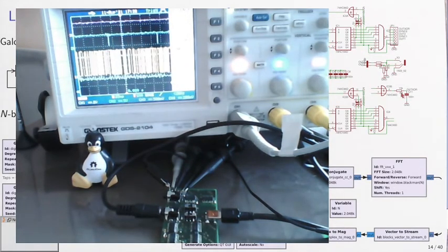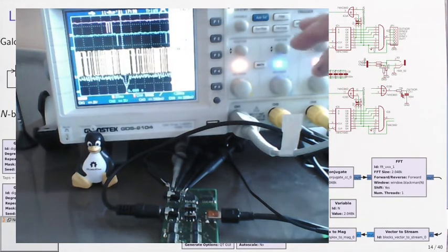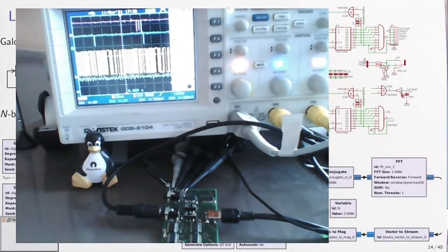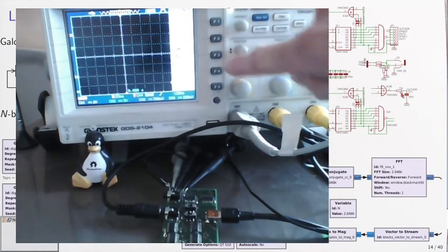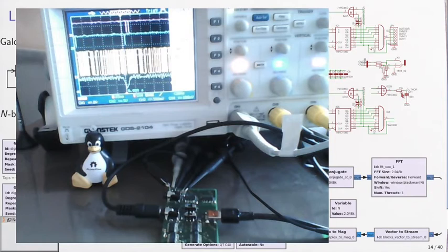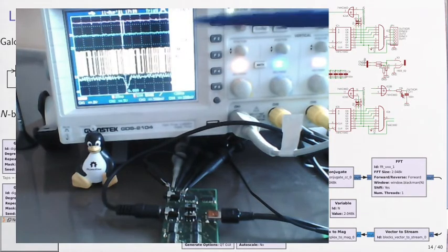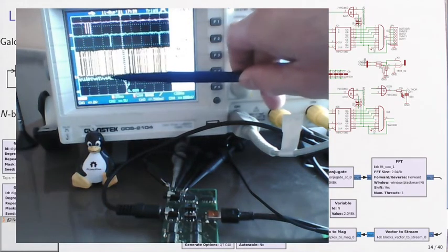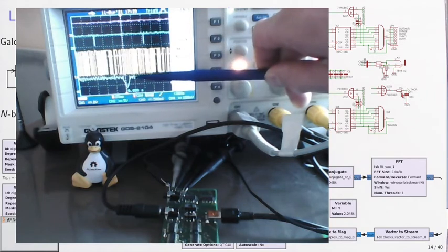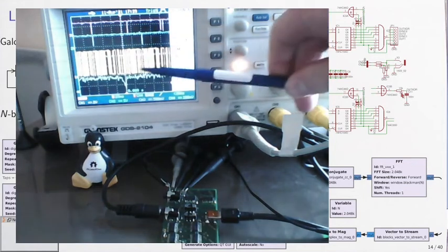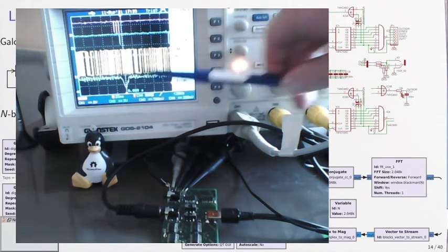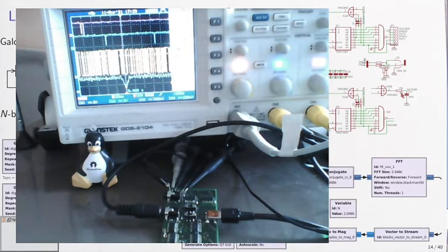So now let us trigger on this low-pass filter output. So if I take the trigger signal and set it to normal mode over here, now what we see is that whenever the two sequences match, instead of having a mean value of 0.5, half the voltage, which is the mean value of 0, 1, or 1, 0, and 1, 1 and 0, 0 at the XOR output, we see that when the two patterns match, all the XOR output will be 0 and the average will be 0.